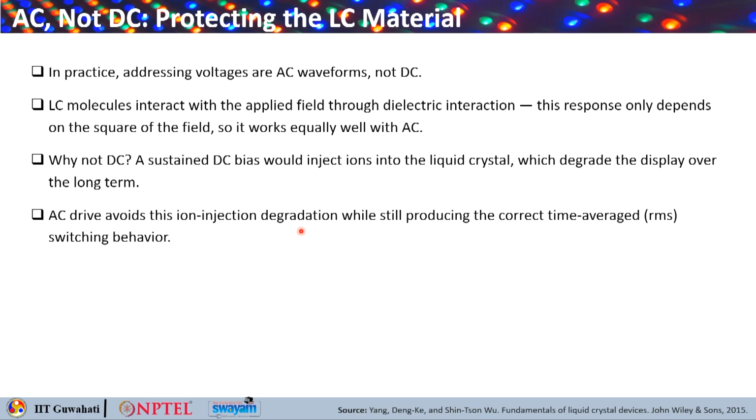It's a slow and cumulative failure mode. So AC driving neatly sidesteps this degradation mechanism while still producing the same time averaged RMS driven switching behavior, and this is why every practical LCD screen, including the one we have just derived, is implemented using an AC waveform in real hardware.